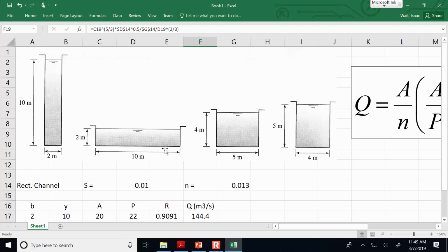Now this one they'd love because it's not too deep and it's easy to build, but it's not as hydraulically efficient. And not only that, a 10-meter wide right-of-way that's meandering through potentially agricultural areas or neighborhoods is going to be really expensive from a real estate perspective. Out west, it's far more common for them to have irrigation canals.